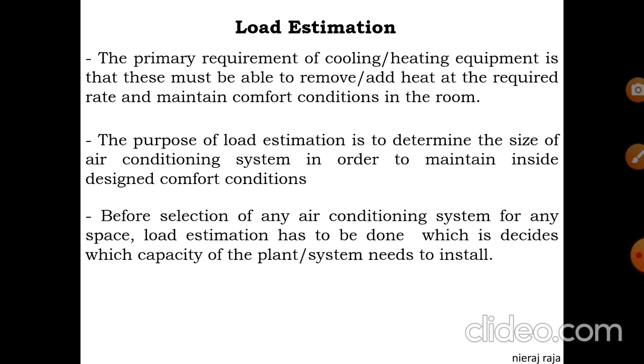Before selecting any air conditioning system for any application, whether comfort air conditioning for your rooms and houses or industrial purposes, the load estimation has to be done, because the load estimation alone decides which capacity is suitable for that particular application. According to that capacity and that load, you decide which air conditioner is suitable for your application.